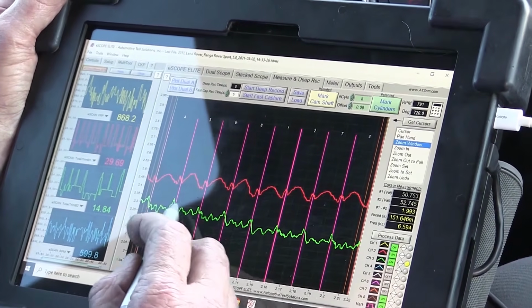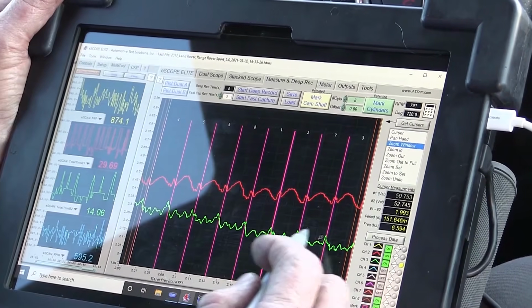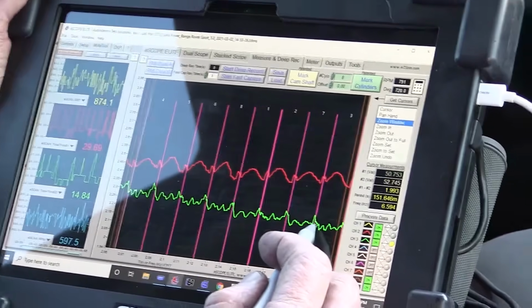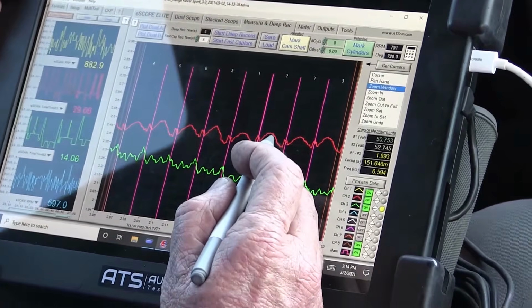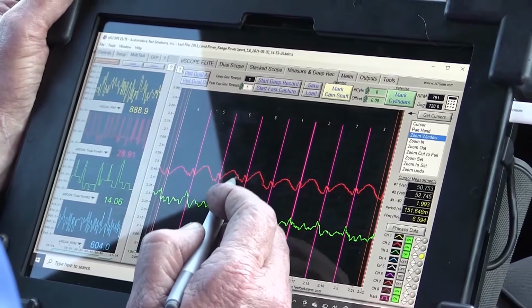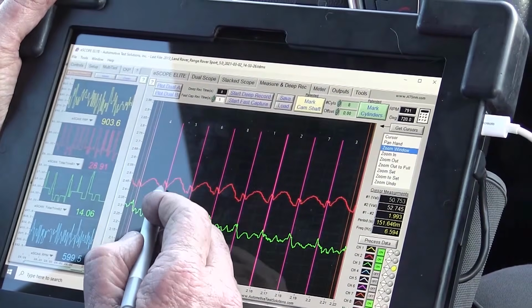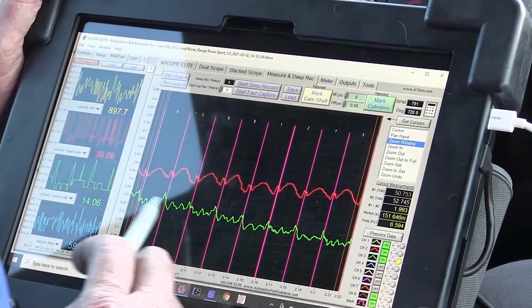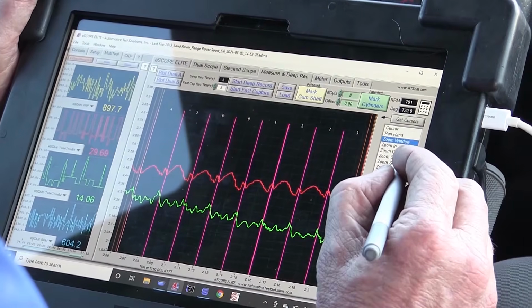There's very little fuel that's going to come back out of this high pressure rail. It's a really high pressure, but there's not a lot of it, so it's hard to change the volume in the low side. But do you see how even and symmetric these all are? Do you see how I've got a hump and a hump and a hump and a hump? So that's what I expect. And this is when we're not having our problem.